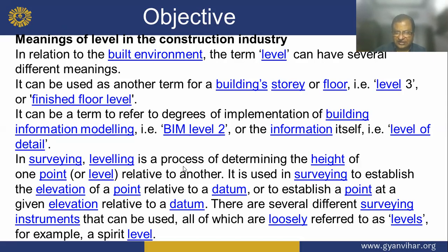It is used in surveying to establish the elevation of a point relative to a datum, or to establish a point of a given elevation relative to a datum. There are several different surveying instruments that can be used, all of which are loosely referred to as a level, for example the spirit level.